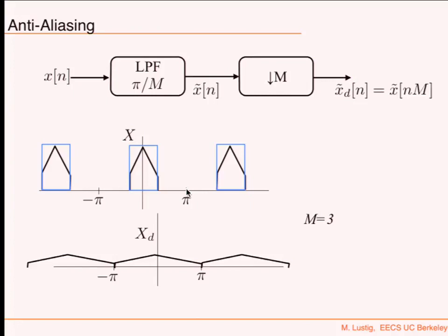That's basically it. And so, in the lab, you're going to have a 240 kilohertz signal. You're going to end up with 48 kilohertz. That is a factor of 5. What will you need to do before you downsample? You're going to low-pass filter, because you're going to have a lot of crap in the other frequencies too that you want to get rid of.